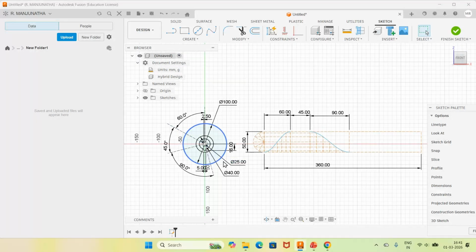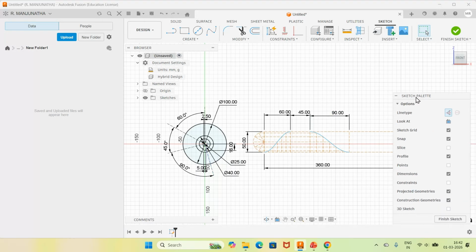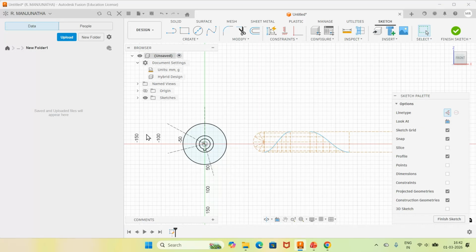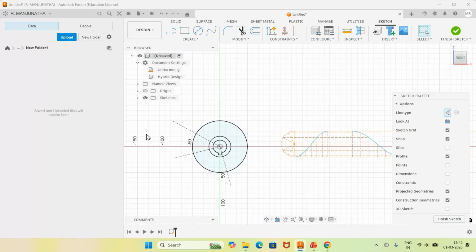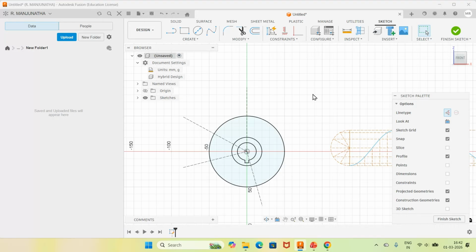That is from here to here, you will have the radius. Already the cam profile has been generated between these two. But the remaining 3 portions, I need to do that. So again, I will just go for dimensions and remove the dimensions now. So now I want to divide this segment. So I will go for trim these portions now.